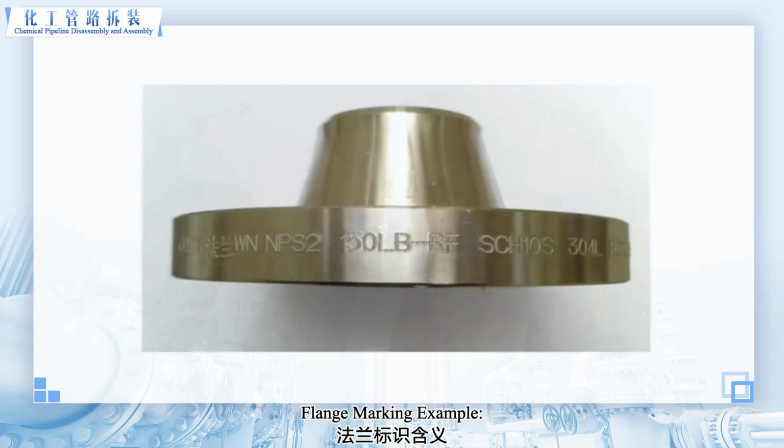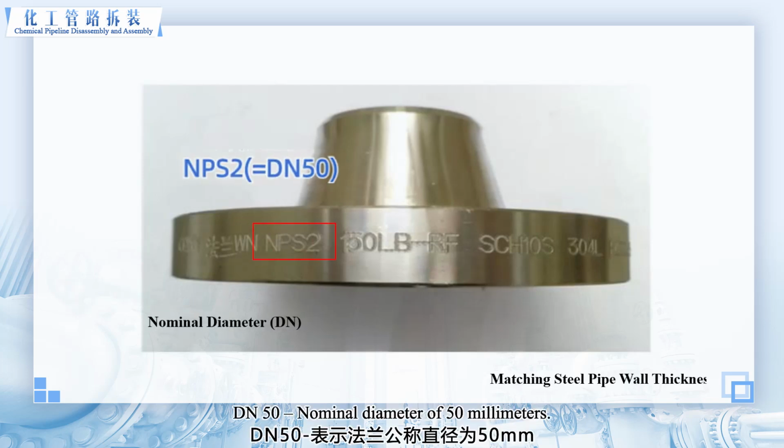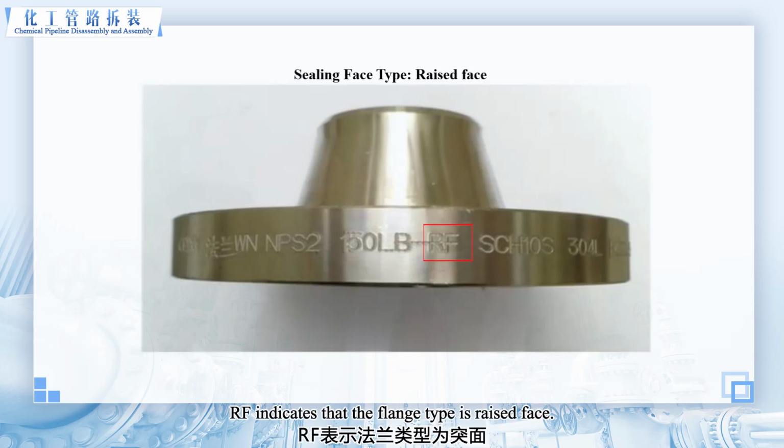Flange marking example. WN indicates a welding neck flange. DN 50: nominal diameter of 50 mm. 150 lb: pressure rating of 150 pounds. 304: material is 304 stainless steel. RF indicates that the flange type is raised face.